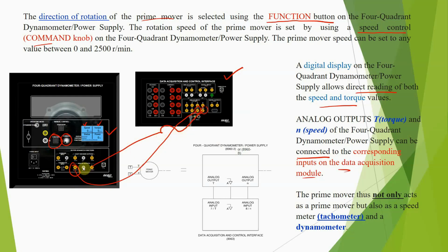And of course, you need to connect the ground to the analog ground also here. This is the analog ground. And this one is connected to the computer. So you can see the torque also in the metering window, and you can also see it from here. Basically, we will use the metering window as our counter-check of the values, and we can also obtain the measurement from here.